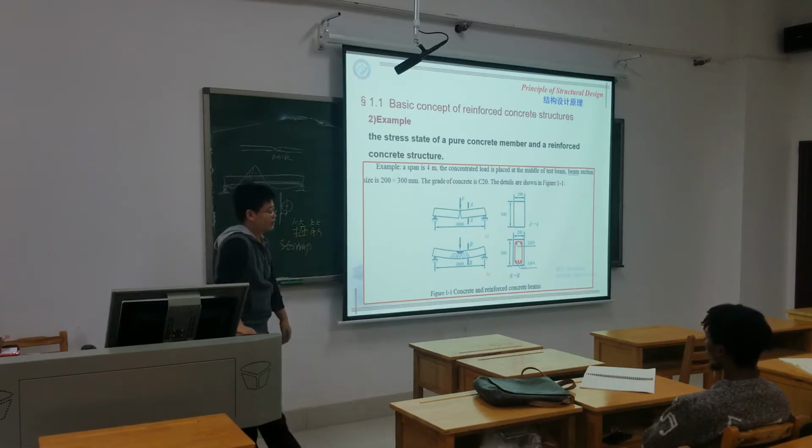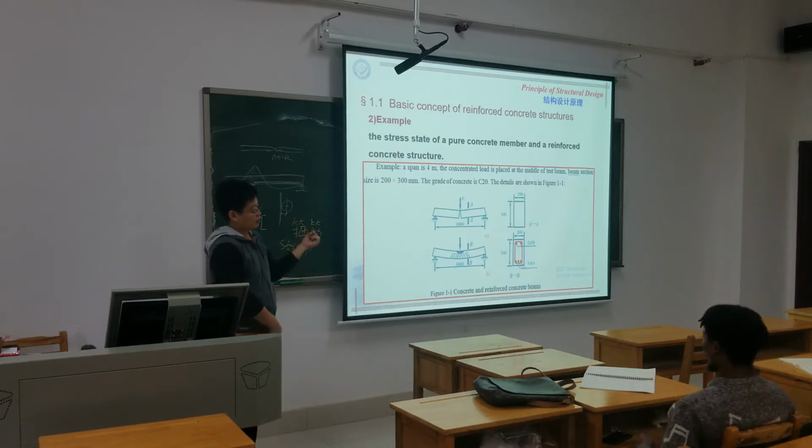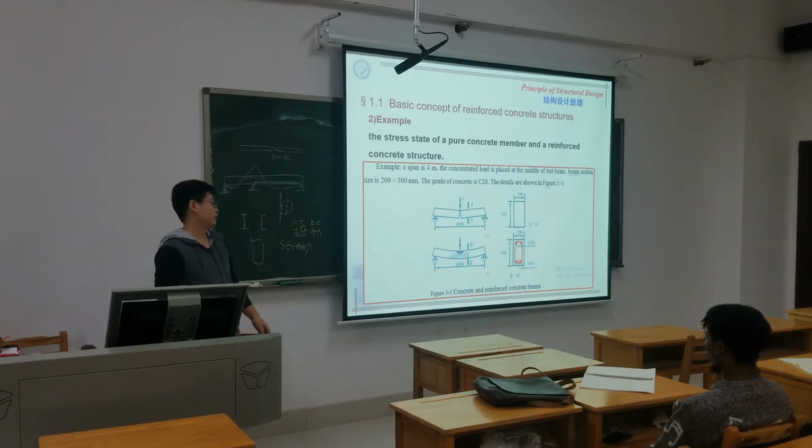So that means when you design the beam, there is a limit, a scope of the reasonable steel ratio, not too much and not too little. That's a very important thing in design. Some people may think, I don't know how to calculate it, just put more steel inside, it's safe. Actually, more steel inside is not really safe. Sometimes it may make the structure unsafe.